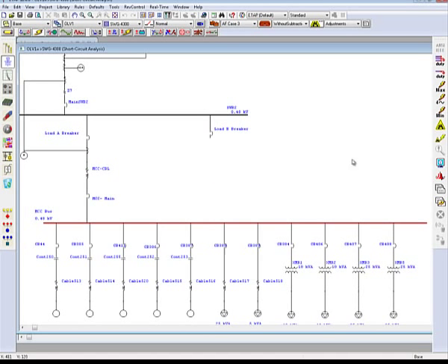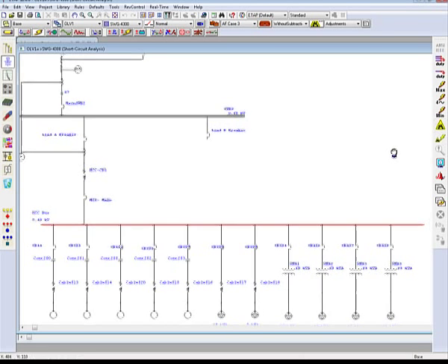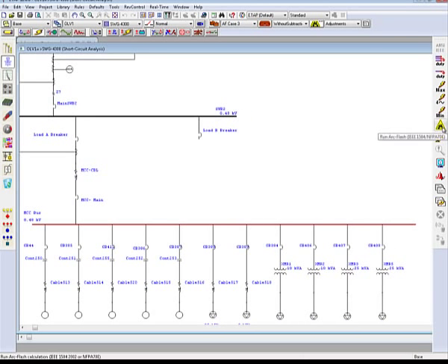We'll run an arc flash analysis, the classical method of just running the triangle with an arc flash. The results are shown and the device is operating at 135 milliseconds. Everything seems okay. Let's confirm the operation of the device by running a sequence of operation.